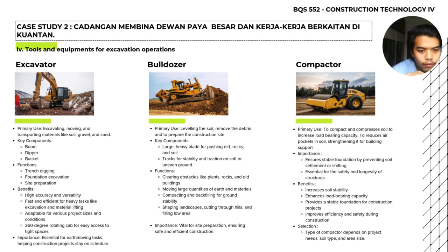So the benefit of the compactor is it can increase soil stability, enhance the load bearing capacity, provide a stable foundation for the construction project, and improve the efficiency and safety during construction. And for the selection, the type of compactor depends on the project needs, type of soil, and size of the construction project.